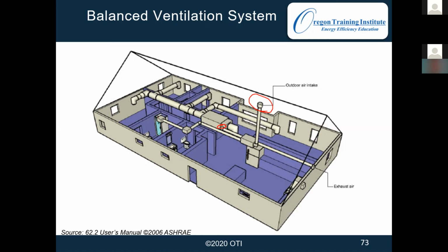On the other side of the system, we're collecting the bad air at the bathrooms, and then they're running through the heat exchanger and going out the sidewall in this case. And that can be good for trying to bring in a lot of mechanical ventilation, more so than a regular bathroom fan could move. We could move several hundred CFM with the HRV versus the 100 or so with the bathroom fan.